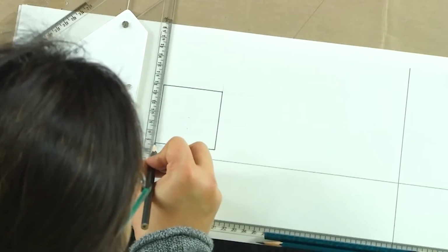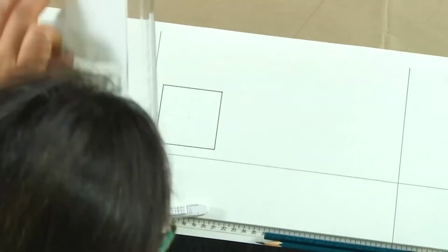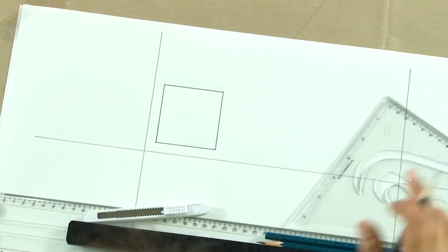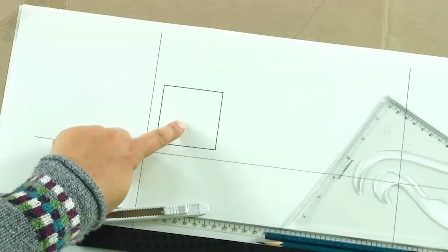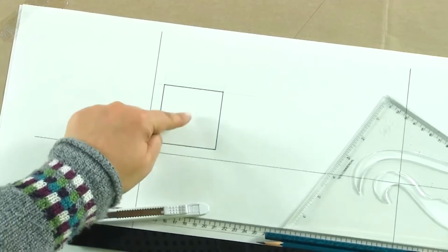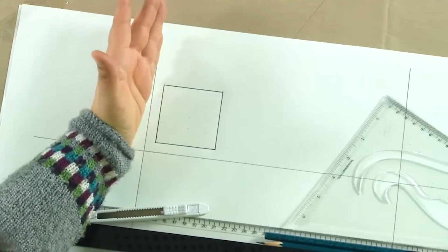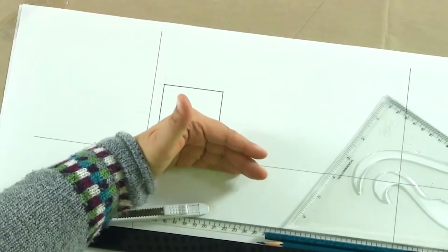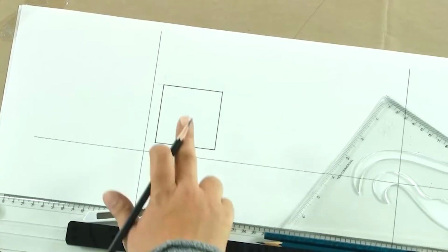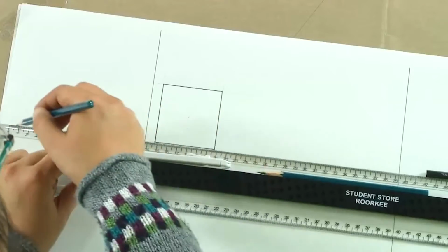Till now we were looking at lines, so there was just one line, but when we start with planes, we will have multiple lines representing one single plane. So, this is the square plane in question. It is 6 centimeter side. Its center is at 4 centimeter from both the reference planes. Now, this is the representation of the vertical plane, and this is the representation of the horizontal plane for this side plane. So, this is what we have already made, and now we will draw the projections onto the VP and HP.